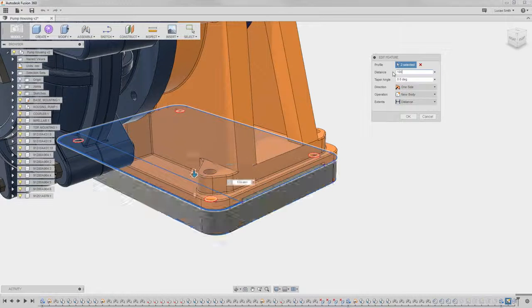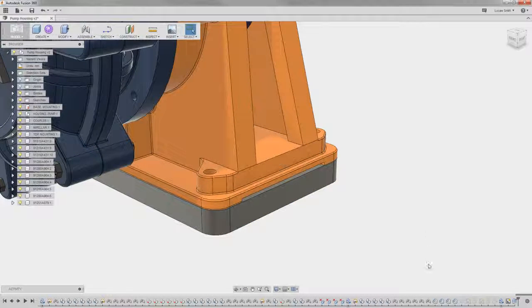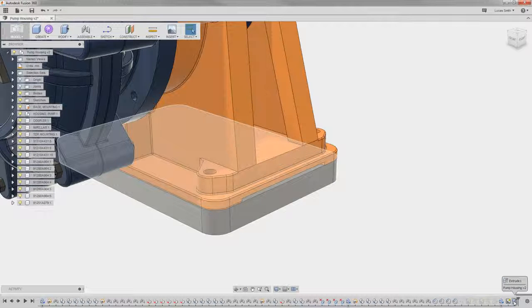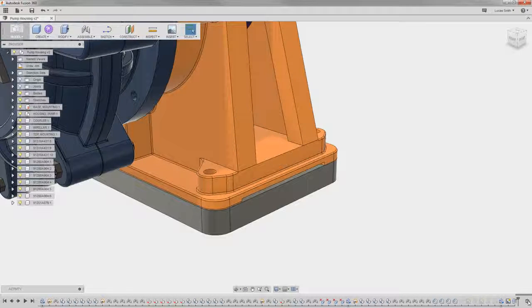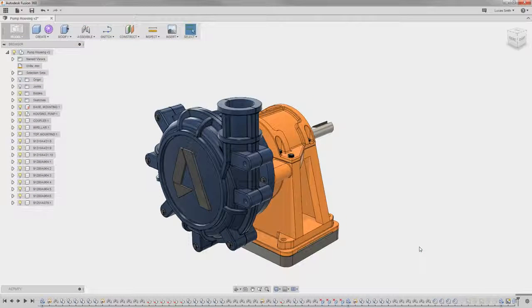As you have probably seen in other history-based CAD systems, this history timeline is where you can roll back and reorder features as needed. And as you continue to add new geometry, features are added to this timeline in order, building off of one another. As you move to the bottom right, you'll notice the gear icon. This gives you options to toggle color assignment to various components, as well as to switch to direct modeling mode by turning the history timeline off. I'll address the advantages of this feature in a later video.